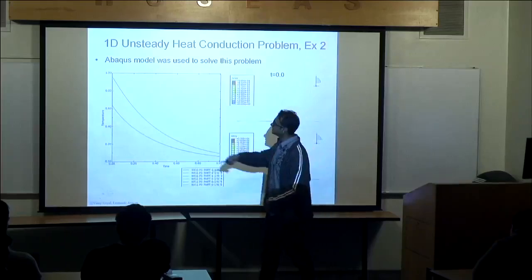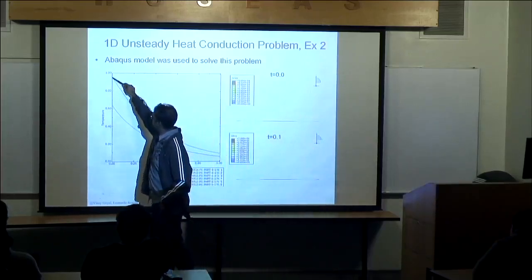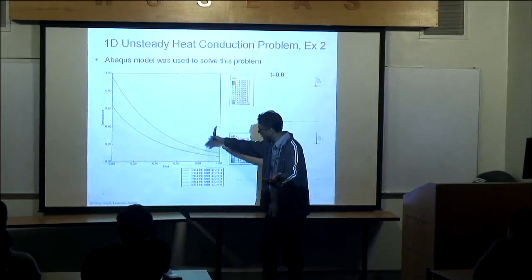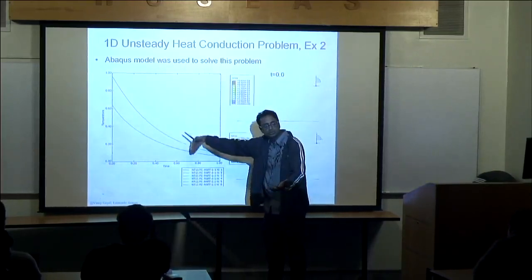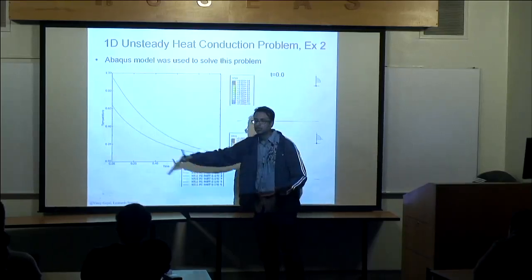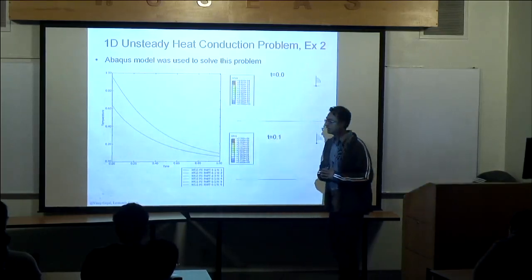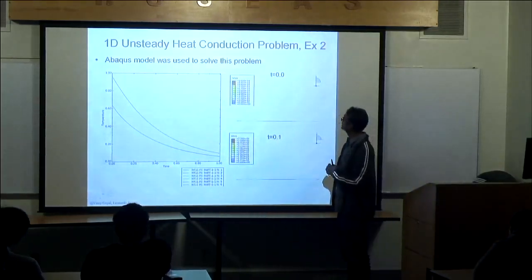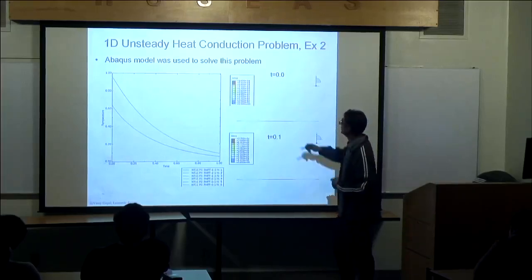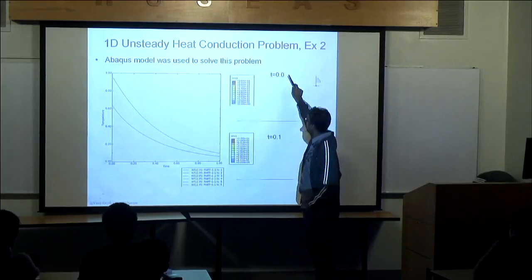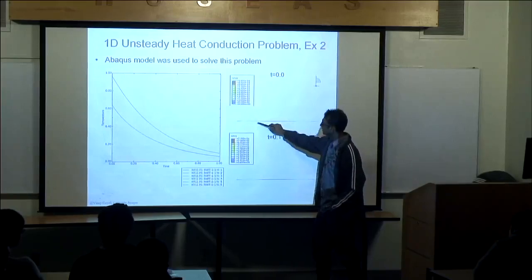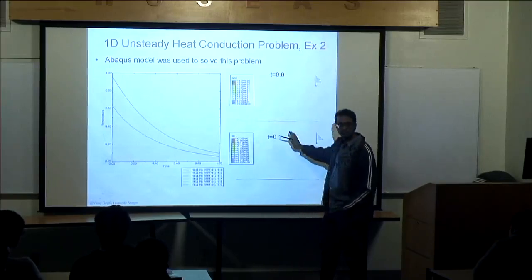And you can see here, I started with those temperatures. It looks right. It drops as a function of time as you expected. It should cool as time goes by, and it should go down to 0 at the very end. I thought this looks correct, actually. Let's look at time equals 0. We should check that. I plotted it also as a contour plot. You can see it's warmer in the center, cooler at the 2 ends, right? So that looks right.